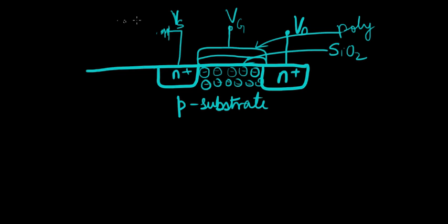Now that you've watched a few videos, I'm sure you're familiar with what's shown here. Just a cross-section of a MOSFET, an NMOS to be specific. We have the source here, the gate here, and the drain. And you do know that this is the depletion layer region. And if we give the gate a lot of positive voltage, you know that it's going to become the inversion layer and start conducting a lot of electrons.